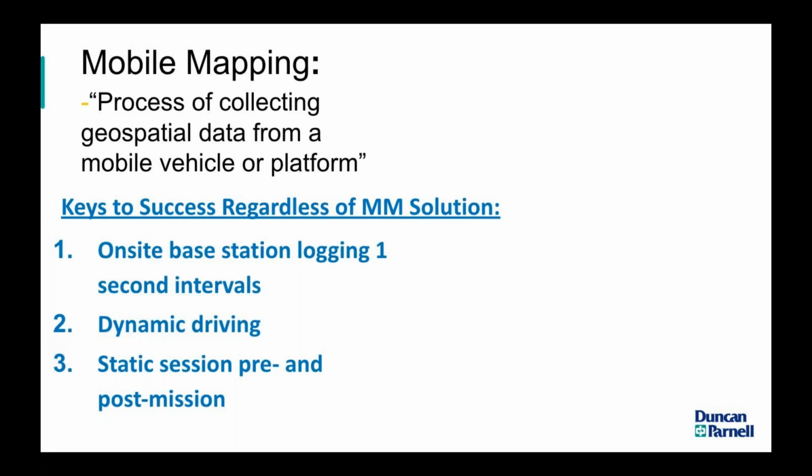And then static session, meaning you've parked under open skies, right? Just to help capture as many satellites as possible to further refine your positioning solution. So again, that's great advice, regardless of which mobile mapping system, Trimble or otherwise, you may use.